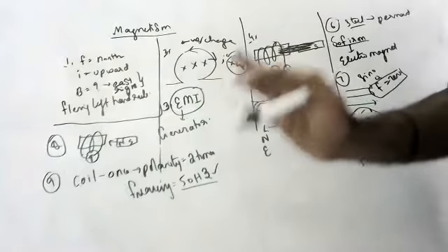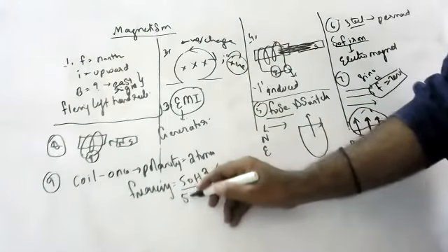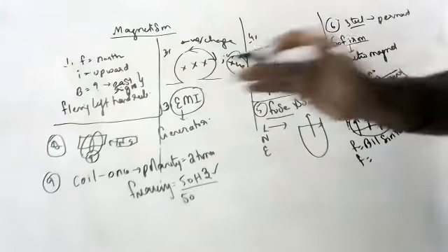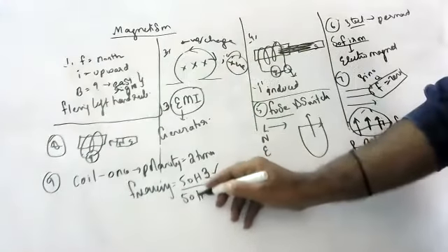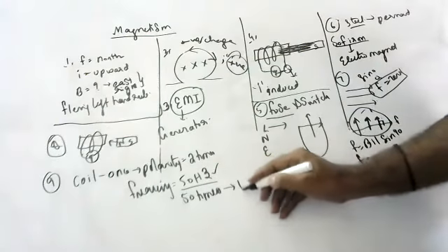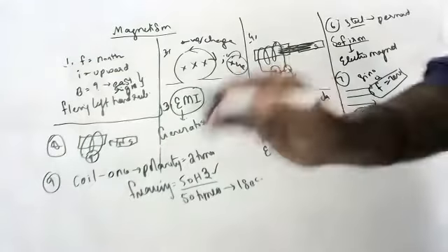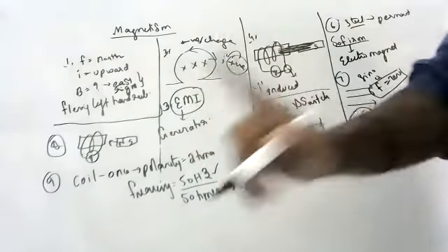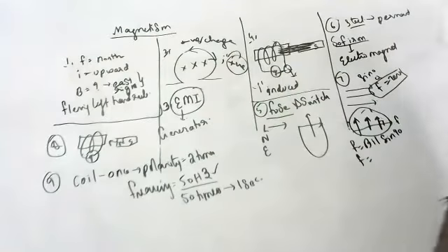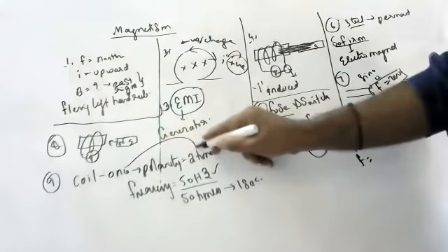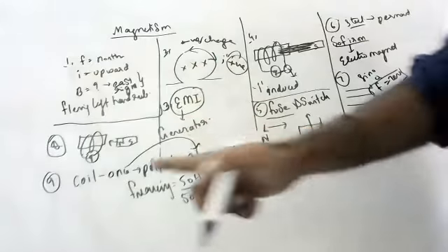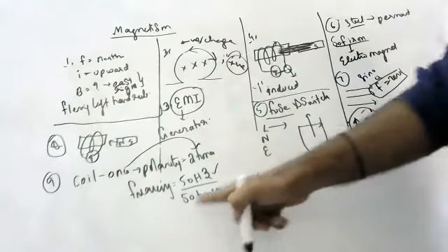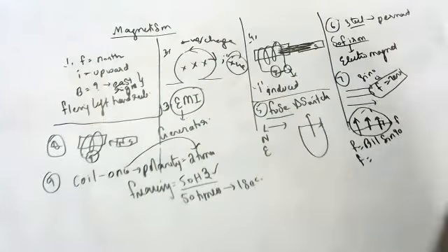50 hertz frequency means our coil in the generator, which is producing 220 volts, rotates 50 times in 1 second, children. That is the meaning. 50 hertz current means the coil inside the generator is moving 50 times in 1 second. One rotation, two times polarity changes, no, children? One rotation, two times. So for 50 rotations, how many times does polarity change?